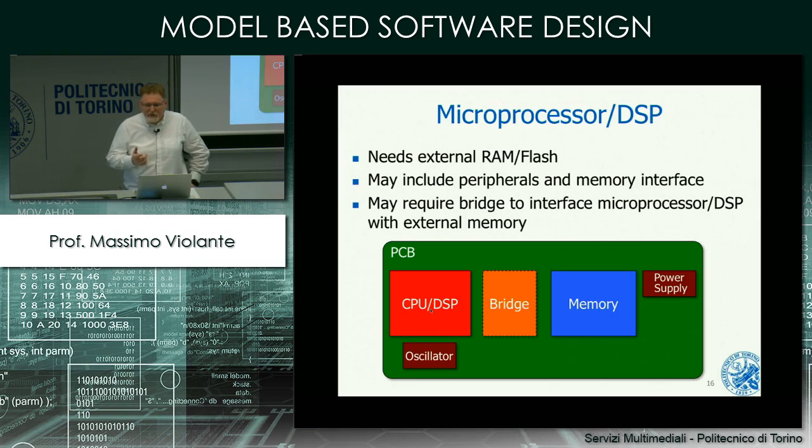But then you have to test the hardware to check whether it is working, because you don't want to ship faulty hardware to your customer. So the more components you have, the more you have to test, and so the higher will be the cost. So the fact that you are using a microcontroller doesn't just make the PCB simpler and the bill of materials shorter. It also gives you significant advantages on the production side and the production cost, okay? So this is something that you have to envision.